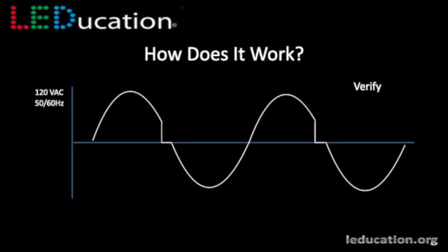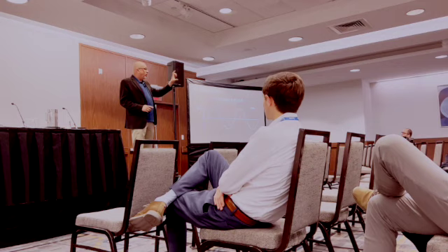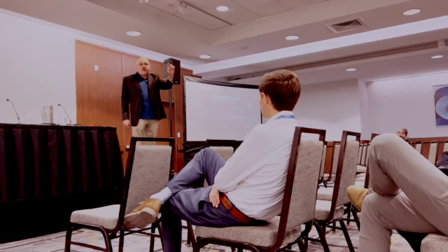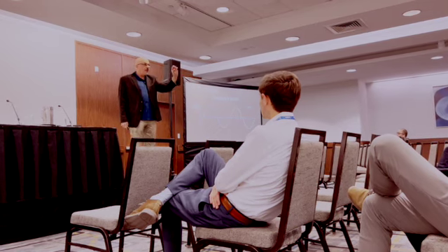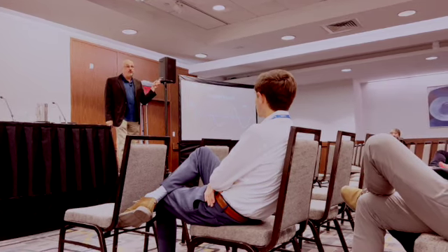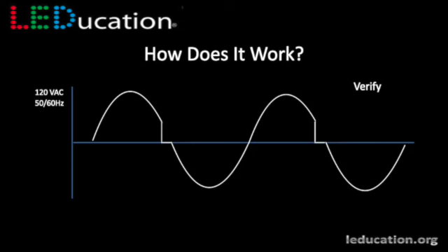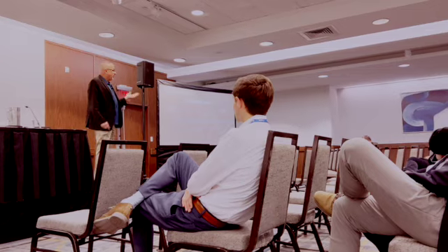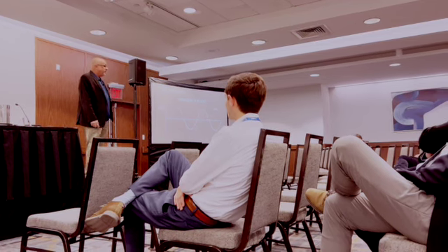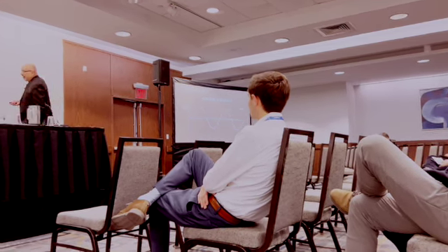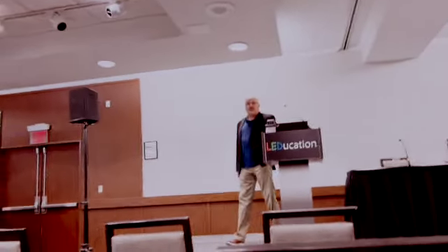So what's happening now is I'm getting probably 4 sequences in a row of a perfect little chunk, not enough to even affect anything power-wise, of a perfect little chunk of our sine wave being taken out. And that tells the receiver, oh, I saw 4 in a row. This is a real message coming. And they'll now interpret the next 16 sine wave portions as a 16-bit message. Whether there's a chunk there or not a chunk there could mean it's a 1 or a 0. And it'll interpret the next 16 as its message. So now we've got a 16-bit message coming. I'll tell you almost, I'm going to say any lighting control scenario can be configured with a 16-bit message.